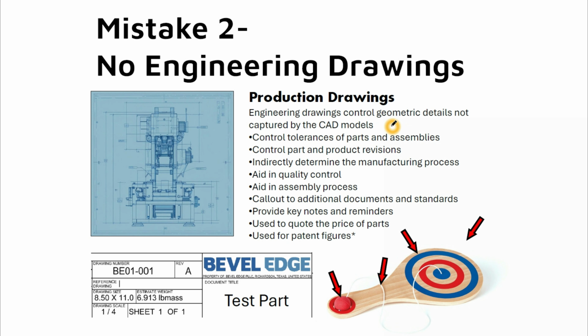And if you don't have an engineering drawing, you are relying on your manufacturer's word to say that, hey, I'm going to make this for you as good as it needs to be. And they could technically start shrinking your paddle over time, and you would have no clue because you don't have a drawing to keep them honest by. And that can make for potentially upset customers, or maybe thin paddles, and now your product is seen as cheap because the manufacturer is cutting cost. And honestly, they can get away with it. Why? Because you never gave them specifications on what the tolerance is. They can say, well, this is 3/8 of an inch thick. It's just the tolerance is huge.